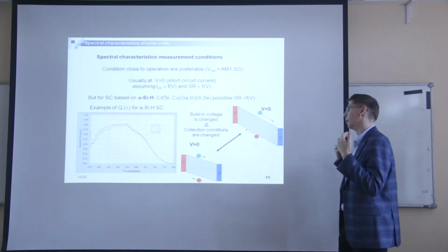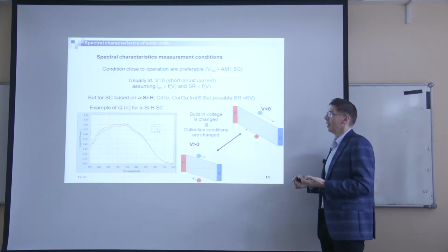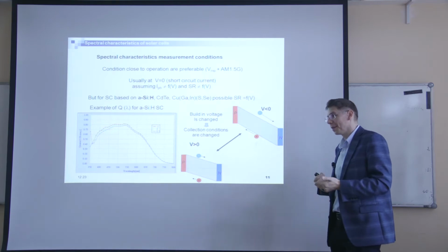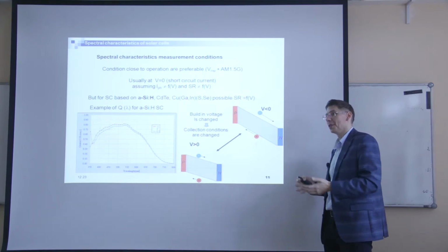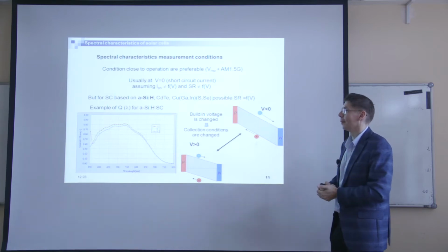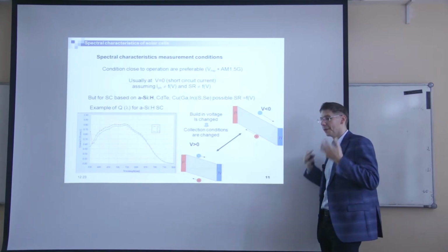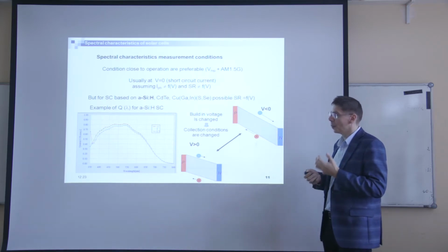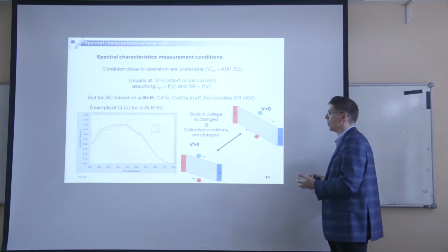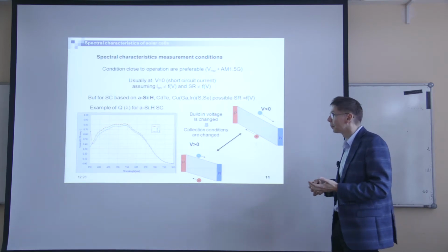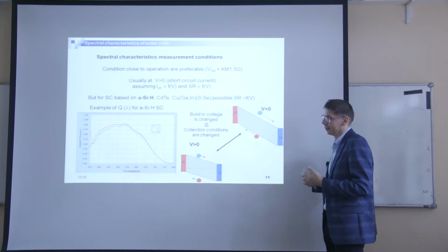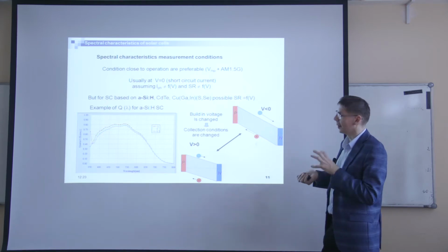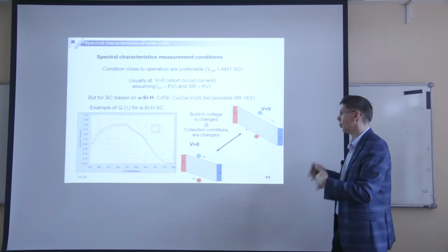Why do we use p-i-n structures? I would say, if we use a p-i-n junction, it means that there is some problem with this material. For example, there are a lot of defects, and the recombination rate is too high. It's a way to increase the efficiency, to increase the short circuit current. But if you have a low recombination rate in the volume, there is no reason to produce the p-i-n junction, because